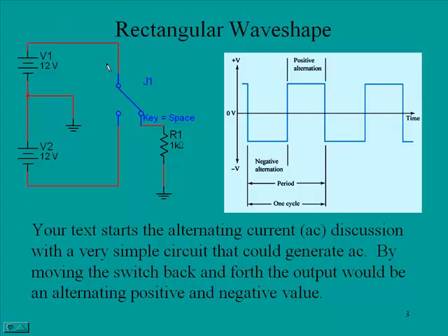By looking at this, we get a sense of the movement of current. So let's take a look at this first. If the switch is in this position, notice we're connected to the positive battery. Remember, current is flowing from negative to positive, so from the negative side of this battery, we would come down through the ground. Remember that from ground to ground, that's the same electrical point.